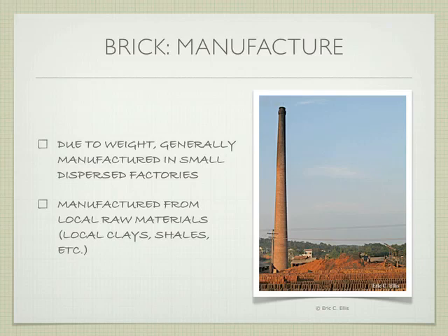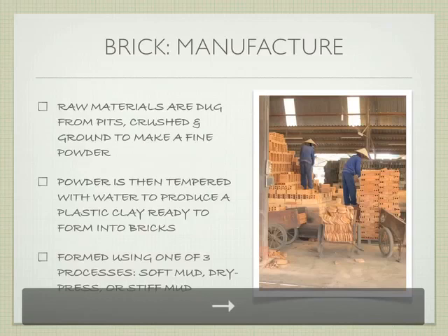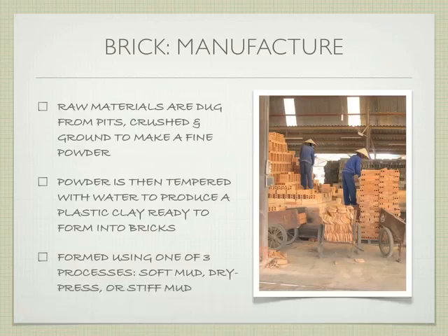That's great. They're also going to be made from local materials because, again, bricks are made primarily from clay, which we'll talk about. You don't want to be shipping the clay from somewhere to make the brick. You want to have a relatively close source for this stuff. So the raw materials are going to be dug from a pit, crushed into a nice fine powder. The powder is then going to have water added to it to make basically mud, a clay, so to speak.